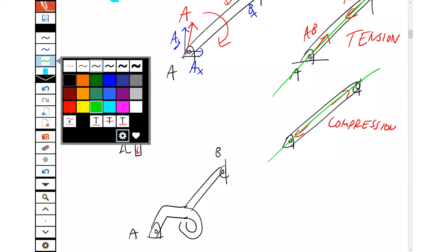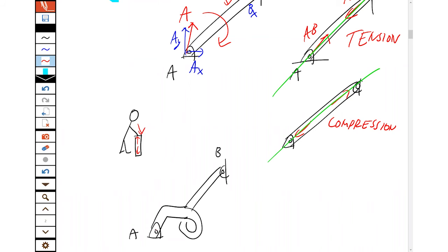I know the forces at A and B, the 2 forces, must be equal and opposite and acting only along the line of the beam. Which again, if you see a very weird looking beam on a question, will make you think, well, hang on, do I really need the shape of that beam at all?